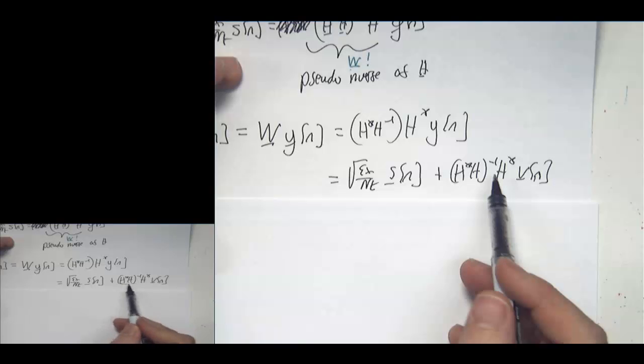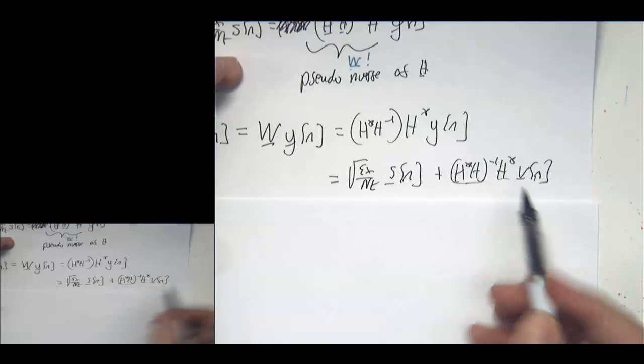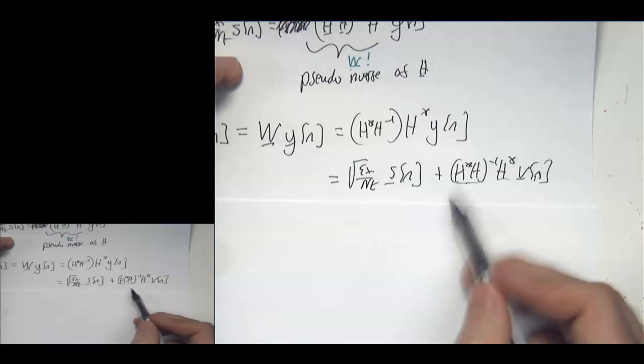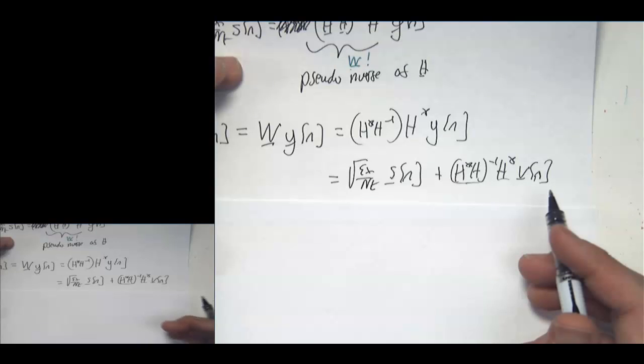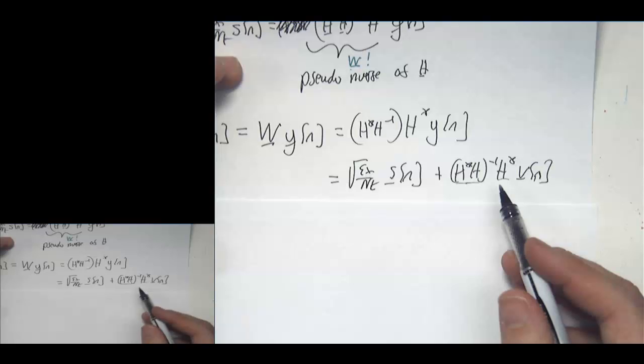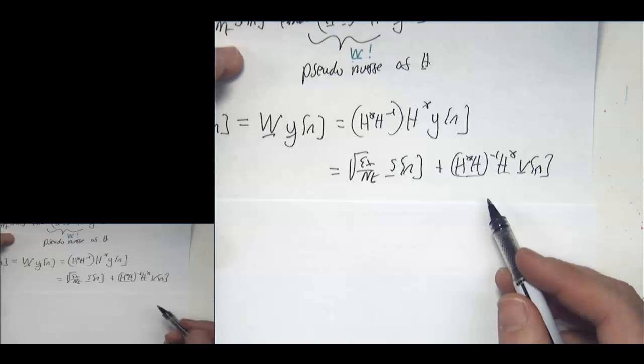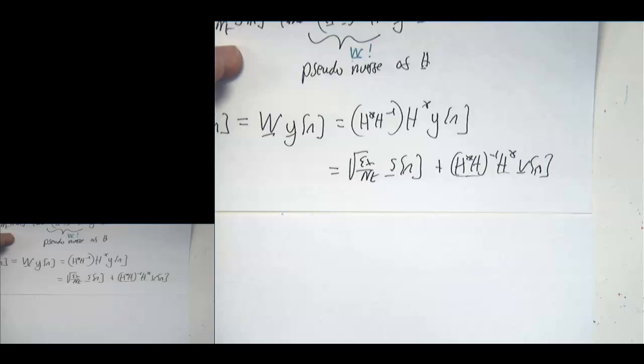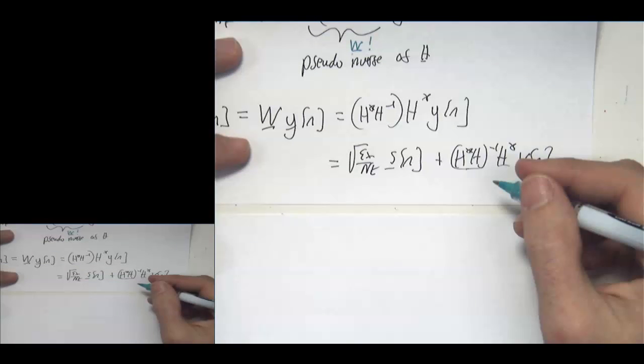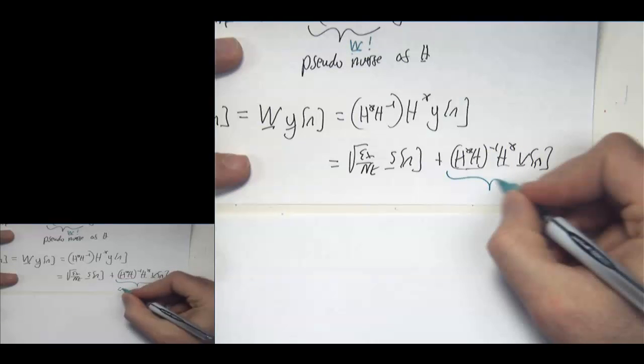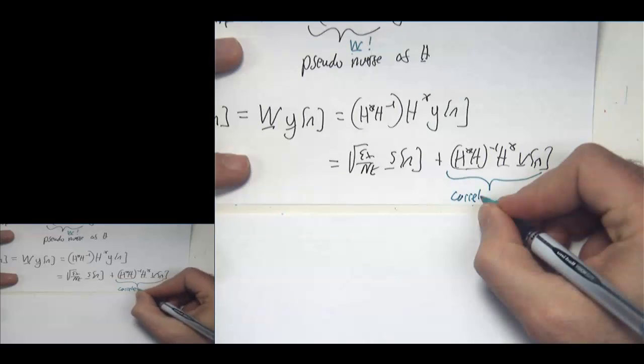With the Alamouti equation, we showed that the noise covariance was also amazingly an identity matrix because of some special orthogonality property. Here, that's not the case. The suboptimality of the zero forcing receiver comes because this ends up being correlated noise, except in very special cases.